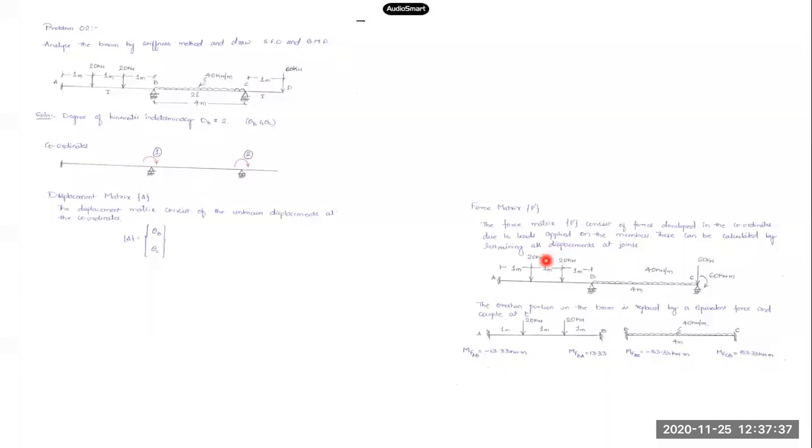Okay, what I can do is in this beam, I can replace that overhang portion by an equivalent force and couple system here. I'll bring this 60 kilonewton force over C. Along with that, what will come is the moment which it was producing when it was at D. When it is at D, it has a moment of 60 into 1 meter, so a 60 kilonewton meter moment is produced at C due to this 60 kilonewton load. Now I'll bring it at joint C itself.